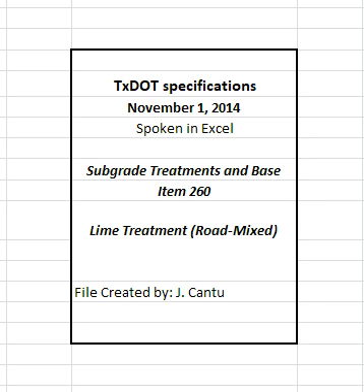Shape and maintain the course and surface in conformity with the typical sections, lines, and grades shown on the plans or as directed. Finish grade of constructed subgrade to within 0.1 feet in the cross section and 0.1 feet in 16 feet measured longitudinally. Correct grade deviations of constructed base greater than 1/4 inches in 16 feet measured longitudinally or greater than 1/4 inches over the entire width of the cross section in areas where surfacing is to be placed. Remove excess material, reshape, and roll with a pneumatic tire roller. Correct as directed if material is more than 1/4 inches low.